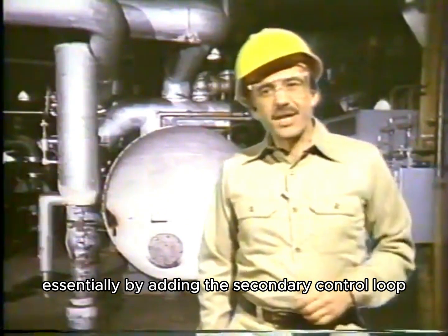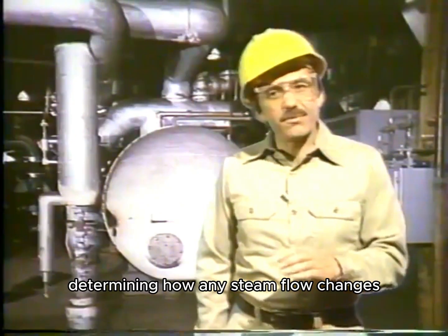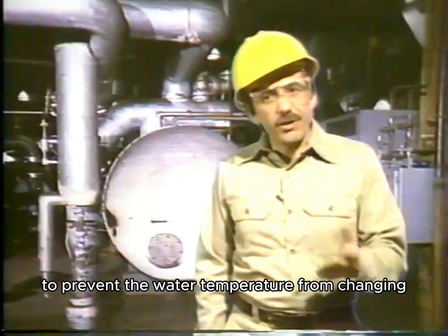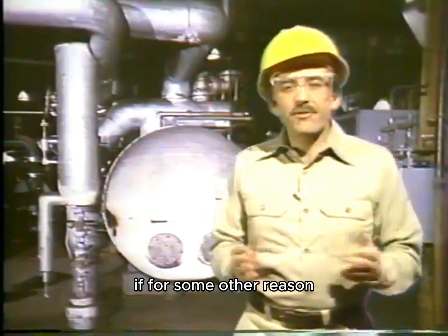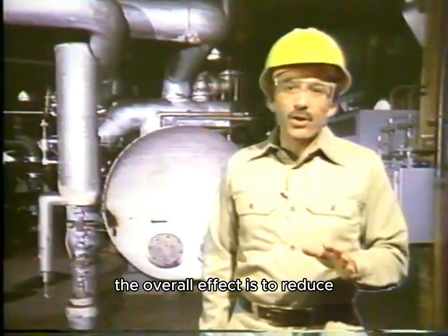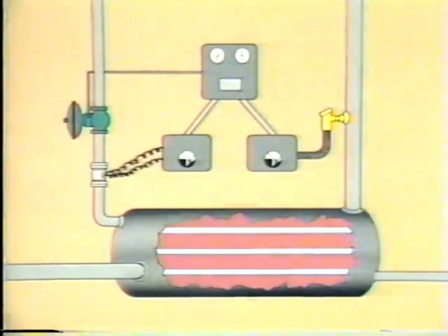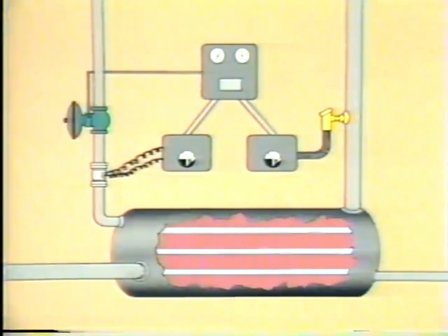Essentially, by adding the secondary control loop, the system is now monitoring steam flow, determining how any steam flow changes might cause the water temperature to change, and providing control to prevent the water temperature from changing because of steam flow variations. If for some other reason the water temperature does change, the primary control loop provides the information needed to correct the error. The overall effect is to reduce the time it takes to sense an error and correct it. Sometimes both the primary and secondary controllers are contained in the same case. This does not change the effect of the control loop.